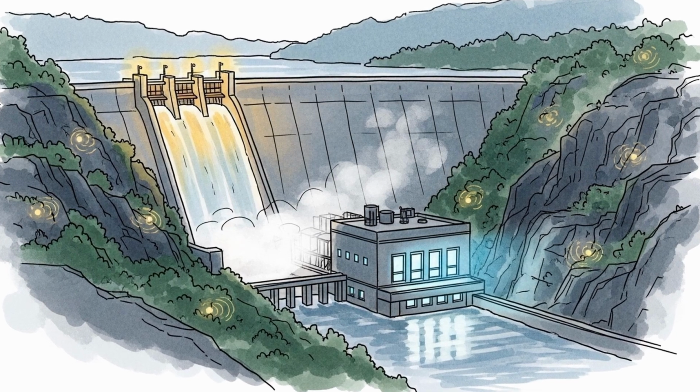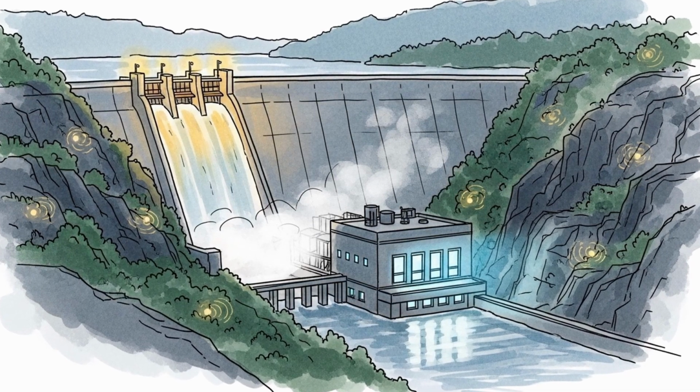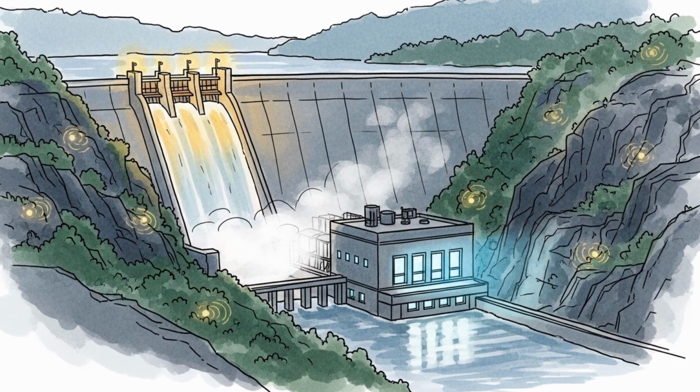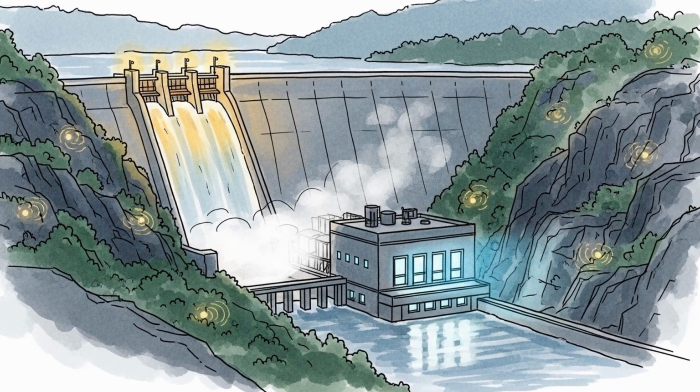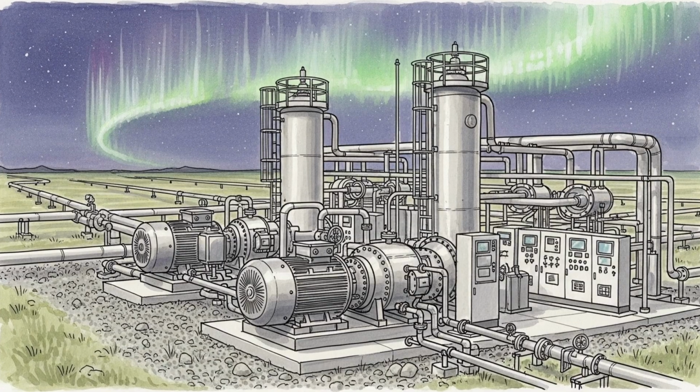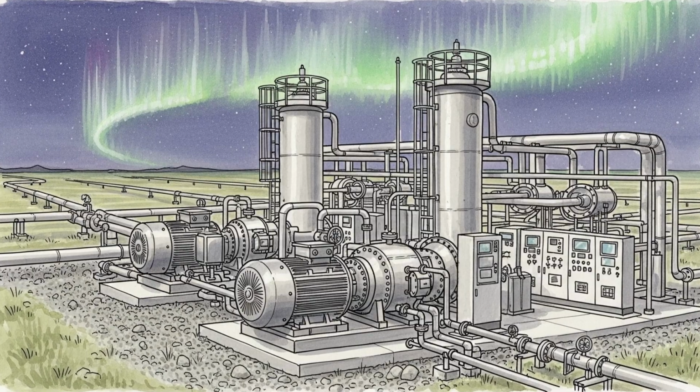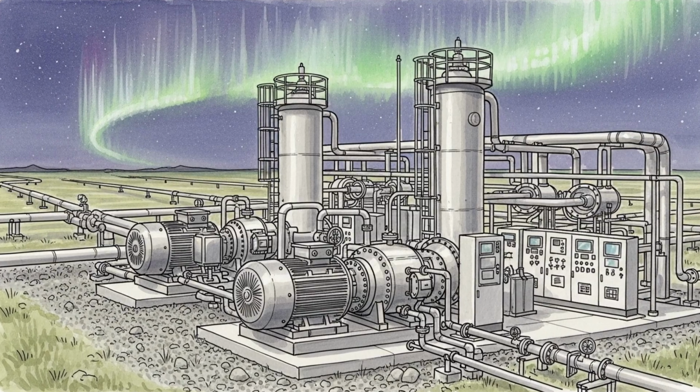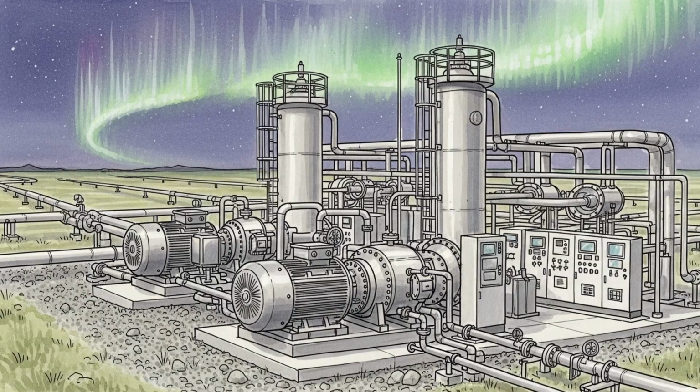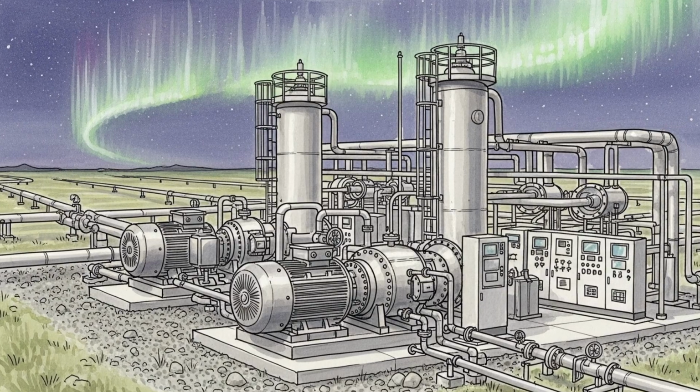They review error counts, reset events, and memory scrub statistics. They compare solar array power and battery performance to pre-event trends. They analyze orbit decay and fuel usage. They recalibrate drag coefficients and attitude control parameters.